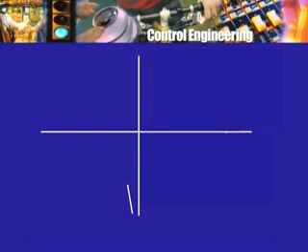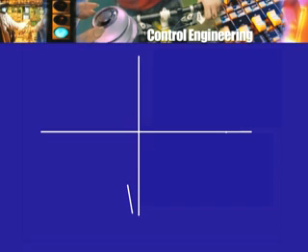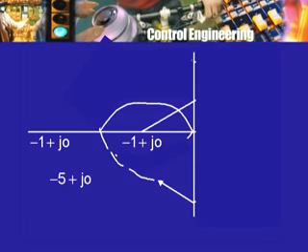This indicates a large value of gain and a phase shift which is very nearly 90 degrees. Of course, I cannot draw a very big diagram here, so you have to imagine that this is really going towards the negative imaginary axis side. So, it starts off from here at low frequencies. At high frequencies, the phase shift is minus 3 pi by 2, the gain is virtually 0. So, the diagram is going to look like what I had drawn earlier, but in between it will have an appearance of perhaps this sort.